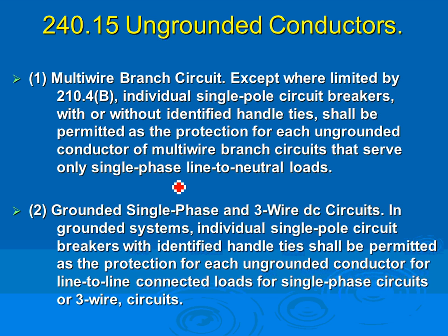You can go as high as 208/120, 208 3-pole tied together with an approved handle to feed a 3-phase 208 system. That's okay. The only time you cannot do it is to feed a 480 system, 2-pole or 3-pole. So if you have a 480 system with 2 hots or 3 hots loads, you have to have a 3-pole circuit breaker. That's what this requirement is telling you.